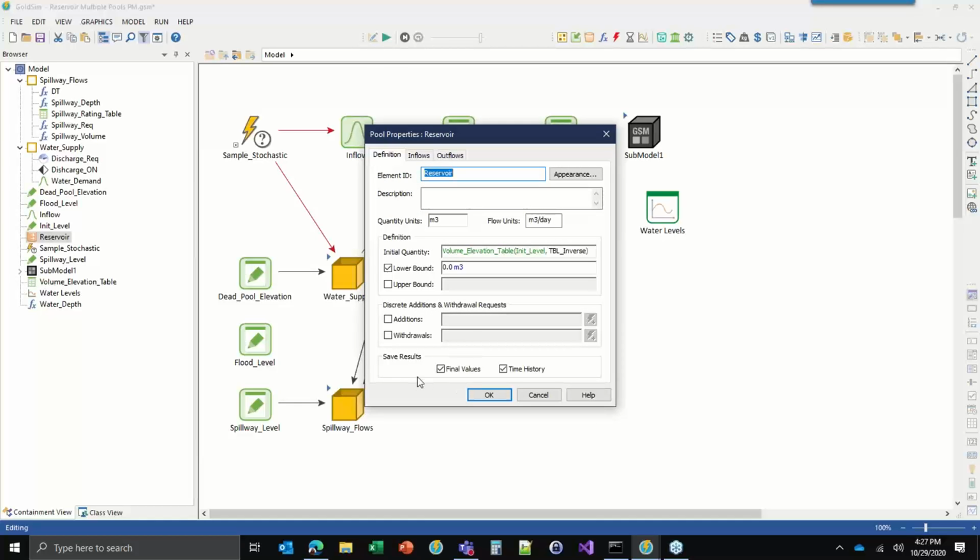And so some people might say, well, you should put the value of the top of the dam. You don't want water to go over. But I would disagree with that. I don't think that's really necessary. To me, that's a bigger problem. I would say that that's a problem with the model. I don't think that'd be something you'd want to, unless you're simulating a dam break, I guess. But other than that, you probably don't want to even be considering that option.